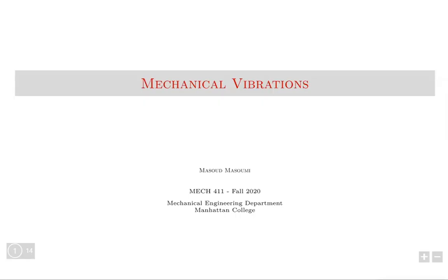So far, we saw spring mass system, we saw spring mass damper system, we saw a pendulum, we saw systems that are mixed, like a bar that is rotating, and it has dampers and springs. We can either use the displacement as the coordinate that we write the equation of motion based on, or we can use the rotation. We typically use the rotation. But in all these systems, one thing was not changing, and that one was initial conditions.